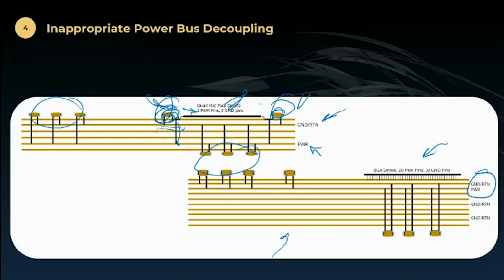And then it's all about the inductance of their connection to the planes. We look at these and say, well, these are right underneath the device, but this is a 14 layer board. Maybe it's 10, anyway, I'll admit we've exaggerated the scale, of course. If that were the whole width, the board's not really that thick. But the components that have to go through vias, 10 layers or so to get to the power planes, that's a lot of inductance. Whereas the capacitors we put on the top layer that are only one layer away from the power-ground plane pair are going to be the ones that respond first, even if they're farther away physically than the ones right under the component. We just need to be aware of that, and depending on what our particular scheme is, we need to do our decoupling appropriately.